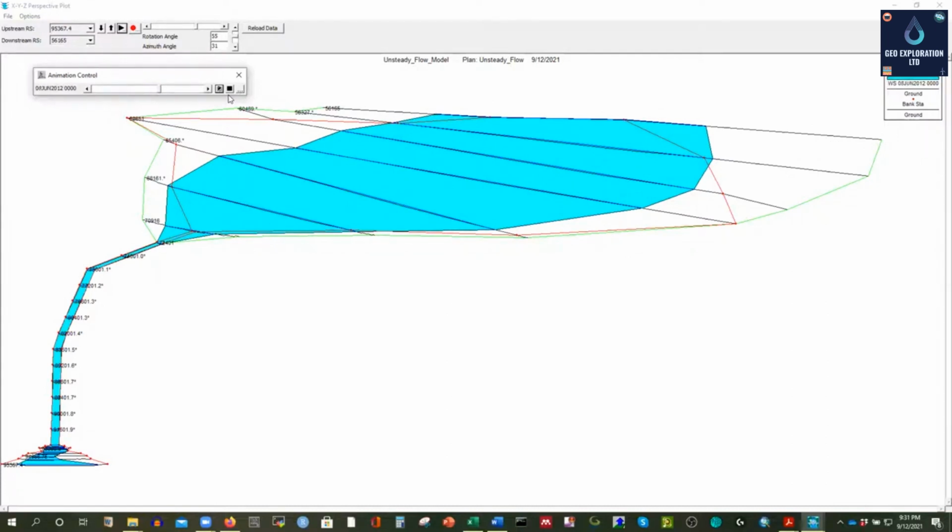We don't need to specify the starting time and the ending time. That's why that is called steady flow, and this is why it is called unsteady flow here, since we have time and the flow condition is changing, basically varying with time. And there will be another flow condition, uniform and non-uniform. Definitely this is not uniform flow, but we can consider this one as uniform flow. For most of the open channel flow, we assume that these are uniform or non-uniform. That is another part of discussion.